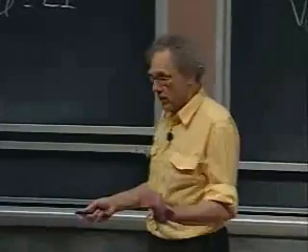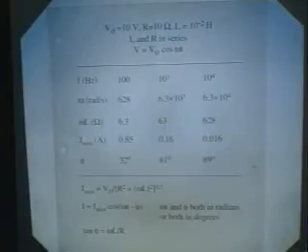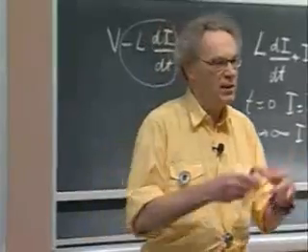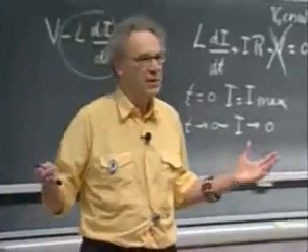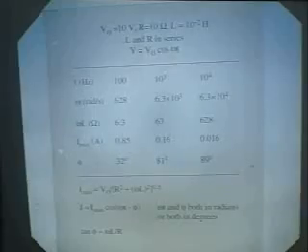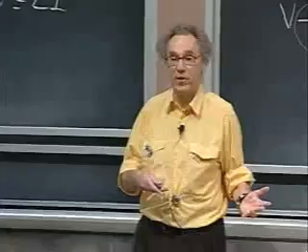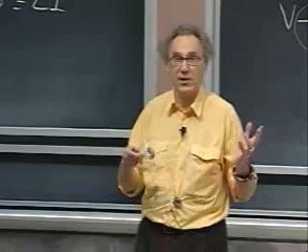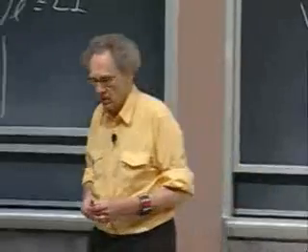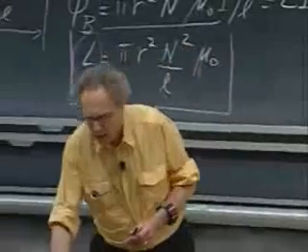And then I will turn on all of a sudden the 10 millihenry. So first I will make you listen to music whereby there is no 10 millihenry in there. And then I will turn on the 10 millihenry, and what you will hear, that the violins disappear. Because the current reduction is now huge on the high frequency, but is very little on the low frequency. And that's the idea of what a self-inductor can do for you. So if you listen to this,